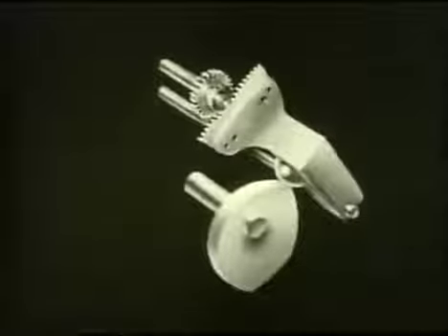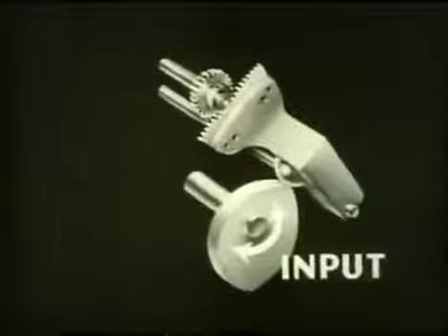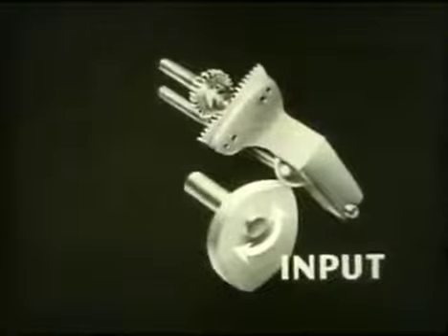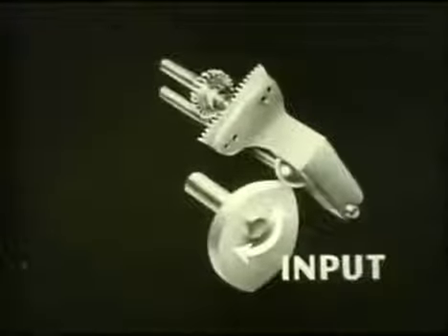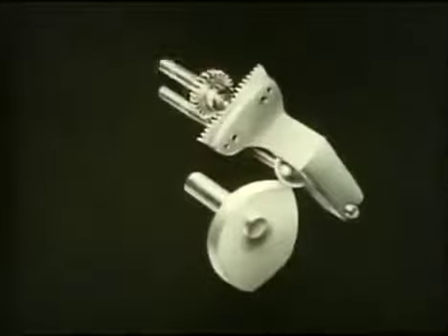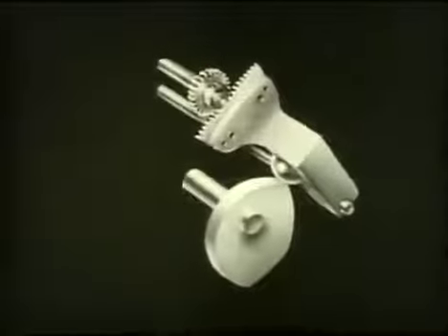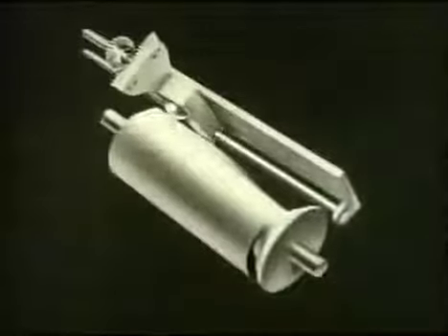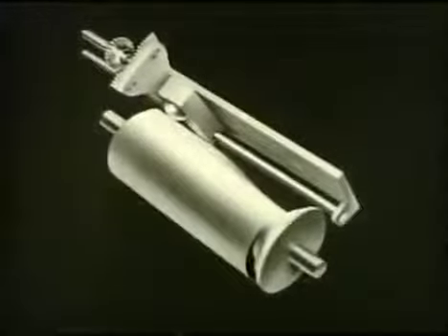In a cam cut for one elevation only, an input would position the cam for advance range, and the working surface would produce the corresponding super elevation output. But this cam is for one elevation only. To handle all elevations, the barrel contains an infinite number of such cams.